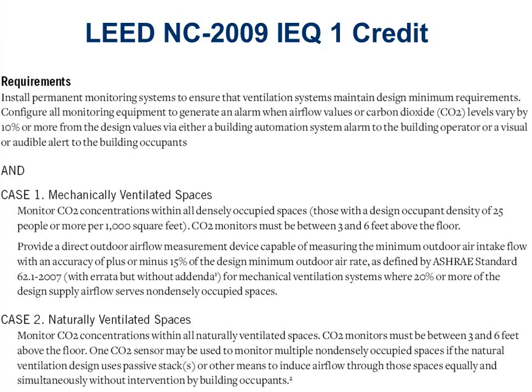The other thing is that they might have put a too low of a set point in to begin with. For some reason, like to Andy's point, I keep finding people that put 700 parts per million in as the set point. And I think that's just a function of them not understanding their own controls device. Usually we're trying to be 700 above the outside air, but somehow they've interpreted it to mean they need to be 700 inside. If it's 700 above and it's 400 outside, that really means 1,100 inside. That's one that causes it to happen quite a bit.